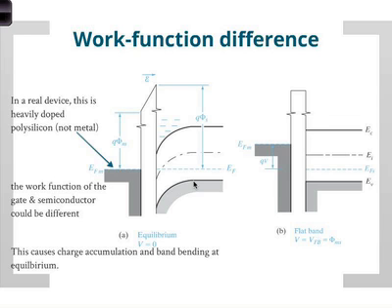So what does that mean? In this situation, the work function of the metal is smaller than the semiconductor. So you have a field which points this direction. The oxide has to bend this way. These bands have to bend down this way. Now, when this band bends down this way, you can see that the intrinsic level has gone down below the Fermi level. So here, of course, it's p-type. Now here it has become n-type, which means you accumulated electrons in that interface without applying any voltage.